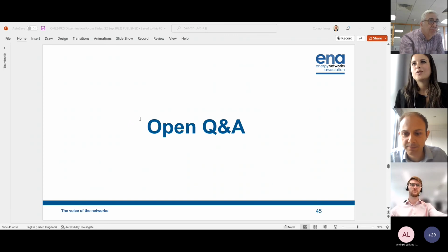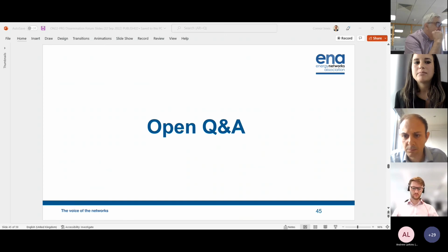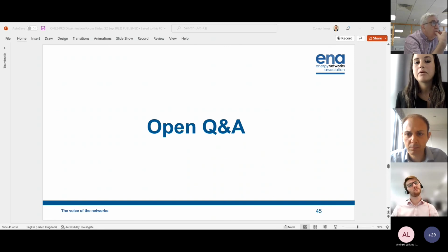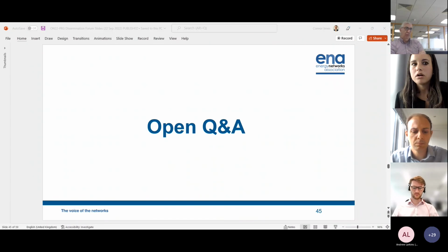Yeah, thank you, Mike, for your question. That's a very good point, actually. This is the starting point where we actually started from: to look at which interfaces different DNOs use to collect data from and exchange data with the customer. Some DNOs use a protocol interface, some others use a hardwire interface, and the implication of protocol versus hardwire is an impact on how many data points can actually be collected, and on scalability going forward.